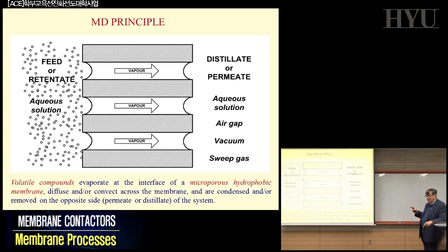We don't have a big problem with concentration polarization here. We don't have any convection, any pressure difference, so there's no convective flux to the feed side boundary layer, and so the traditional fouling is much less severe. But creating a temperature profile can kill the process. Temperature here is acting in two different ways. One, as I told you, a small difference in temperature, delta T, is necessary to move the molecules in the vapor phase from one side to the other.